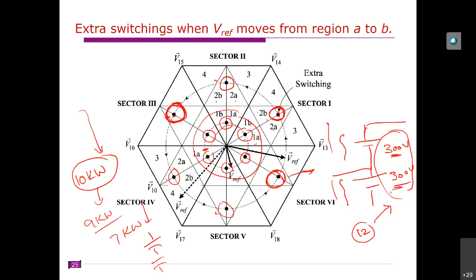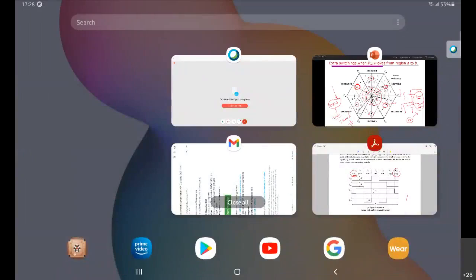That is not required when you have fixed sources, right? Which one is usually better to use, fixed sources or capacitor voltages? That all depends on the application, right? If it is a motor drive, that means continuously you need to feed it, continuously you need to supply power, right? So in that case you need to use an active front end. This is what we discussed, I think.